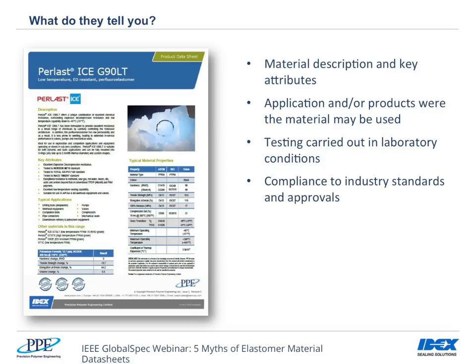Datasheets may also provide some alternate material grades which may be suitable as well. In this case, there is a small area at the bottom where some chemical immersion testing has been carried out and there is some information around that. But on all datasheets there will be a table full of numbers with various properties. This table with these values, although they are correct, they are often misunderstood. Tests that are carried out to determine these values are often carried out under laboratory conditions at very specific temperatures for very specific time periods and under very controlled methods, usually to an ASTM or ISO standard.